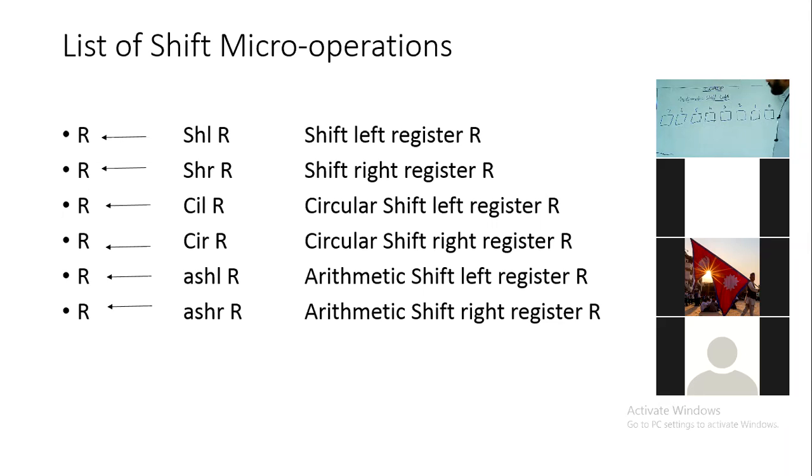Okay. Now how we perform left operation? वैसे तो ये easy है. Left operation हमने क्या करना है? इस तरह, in this way. Shift the number here, insert 0, and this bit is shifted to the position number 1, and this bit is shifted to this, and this, and this, in this way, and the last bit is out from the register and discarded. Okay, in this way we will perform arithmetic shift left.